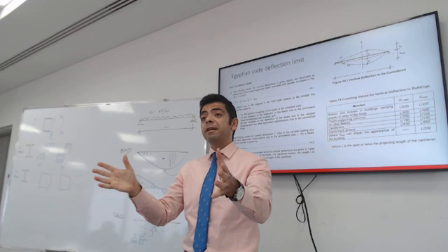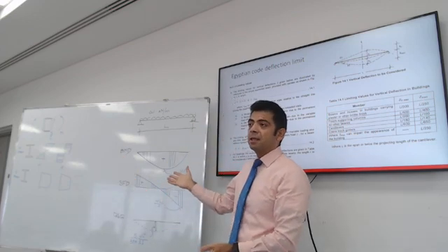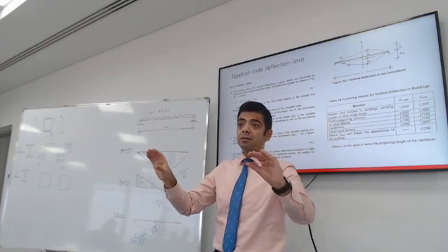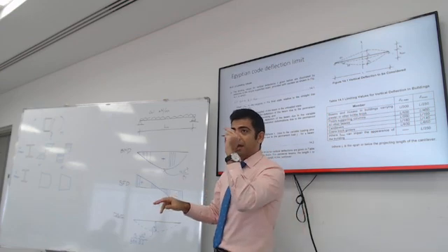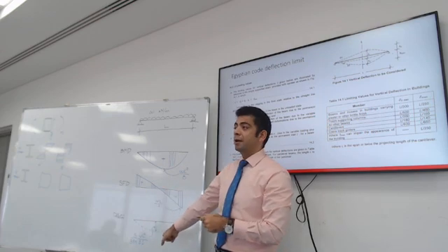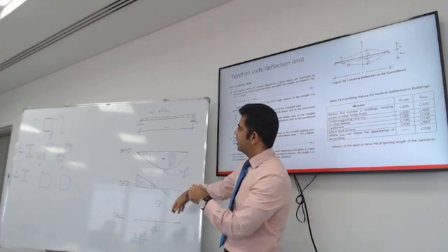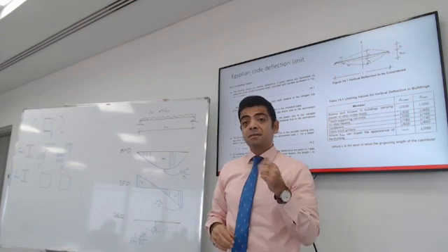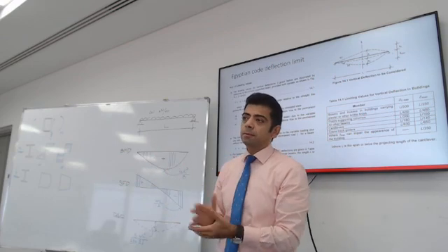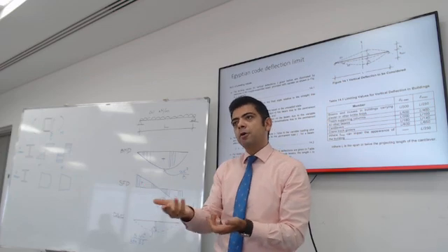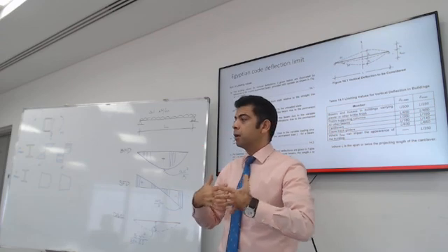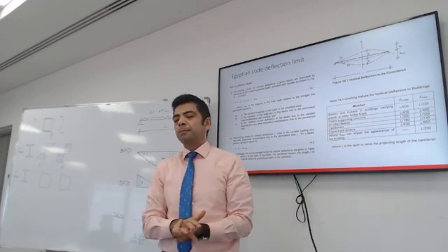All right? So speaking of exams, this is something that you can expect in the upcoming test. I will give you a beam with a load and ask you to design it. And I expect you to check for 3 things. Design it for bending, check shear capacity, and check the deflection. And when you're done with this, now this beam is a safe design for ultimate limit state and serviceability limit state, and then it can be part of a structure. It will be safe for people underneath it and on it, and it will deform and perform according to design. It's not deflecting excessively.